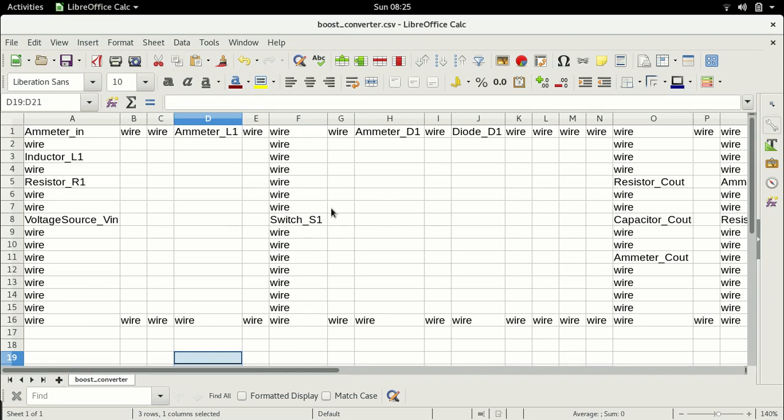So therefore, when you want to boost up the output voltage, you need to take into account that after a certain level, the stresses in the switch will increase to a value which may not be practical, right? And at that level, the switch may get damaged and you may sustain damage in the other parts of the system as well. For example, the diode may also be damaged because the diode is also taking a huge current and also is experiencing a huge reverse recovery voltage. So these are things which you need to take into account.